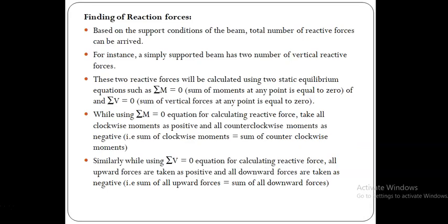Then how can we find the reaction forces? Before analyzing any beam, if you want to find the shear force and bending moment on the beam, we must find the reaction forces. Only by knowing the reaction forces can we calculate the shear forces and bending moment along the spans of the beam. Based on the support condition of the beam, first we have to arrive at the total number of reactive forces.